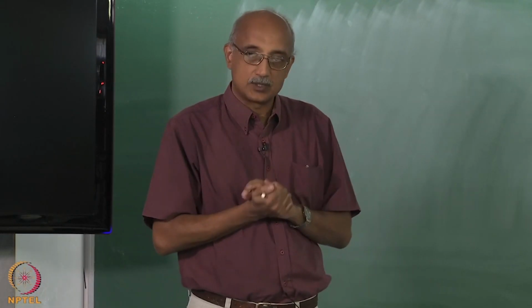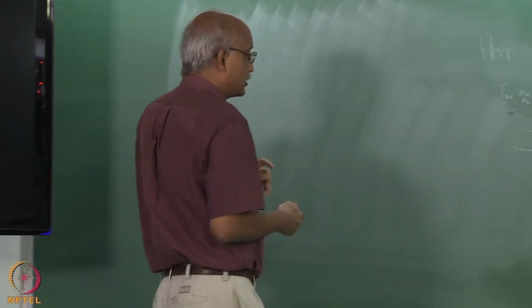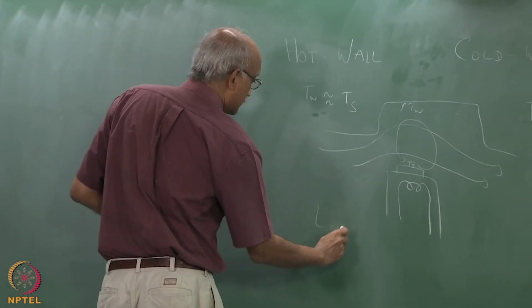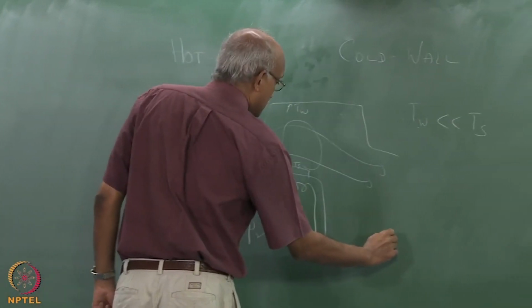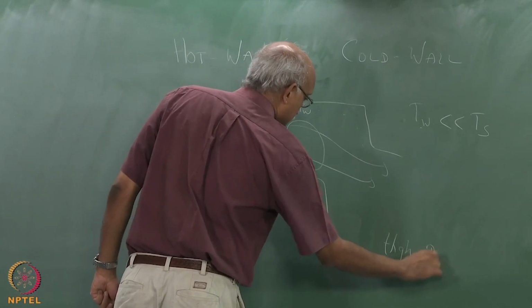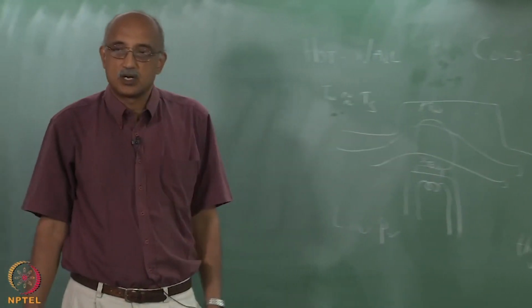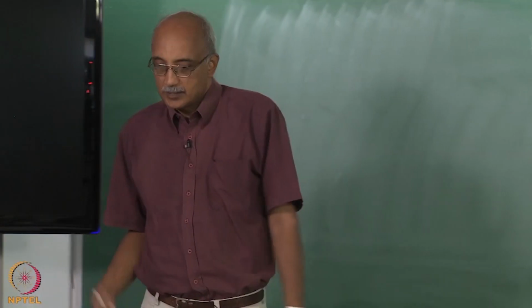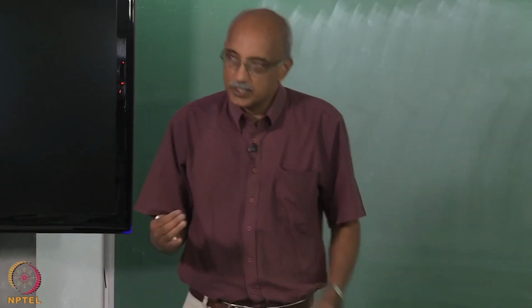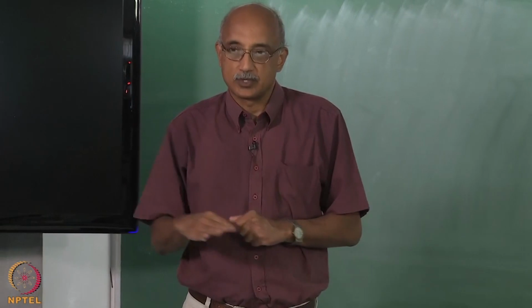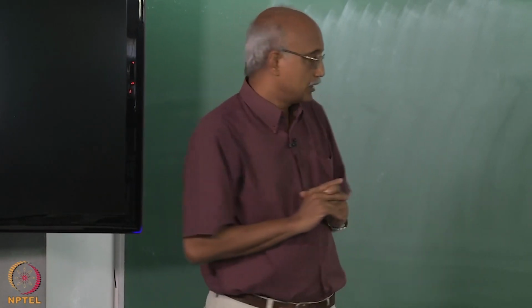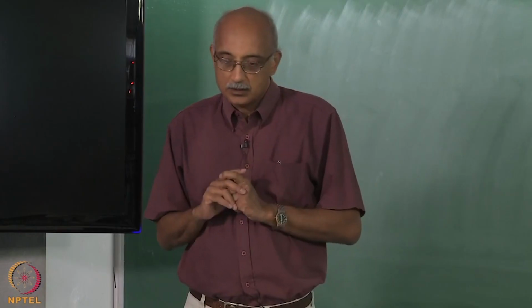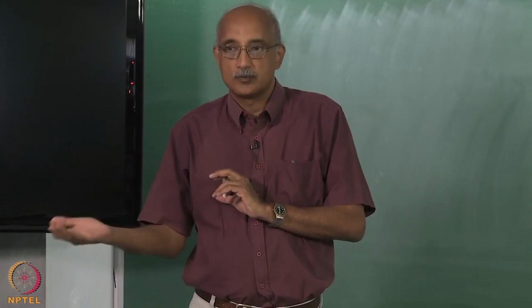Now, how does pressure play into this? When does low pressure help and when does high pressure help? Well, again, pros and cons. When you are, as I mentioned the other day, when I say high pressure in a CVD context, we are really talking about atmospheric pressure, right. Now, under atmospheric pressure conditions, again chemical reactions will run much faster. They are more likely to reach equilibrium, because both pressure and temperature are typically accelerators for chemical reactions.